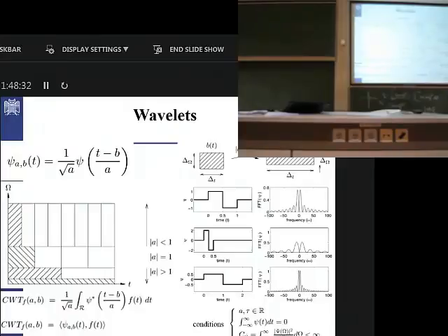So we have filterbanks, we have joint time frequency, and finally we just come up with the wavelets. You'll see that it's quite the same, and it solves almost most of those previous issues that we have as a drawback of Gabor or STFT. So why do we need to have the constant area window? We can just dynamically change it, and that's the idea. For the lower frequencies, we need to have a long time window. The wavelets should be as long as possible to get the lowest component of the signal.